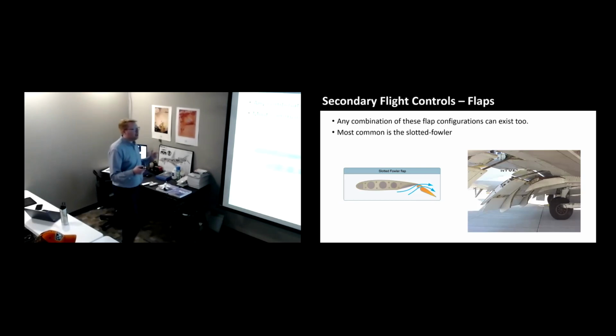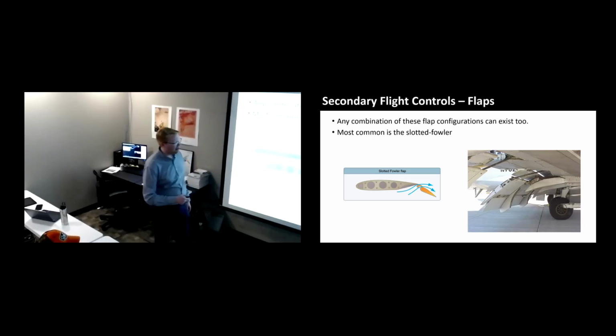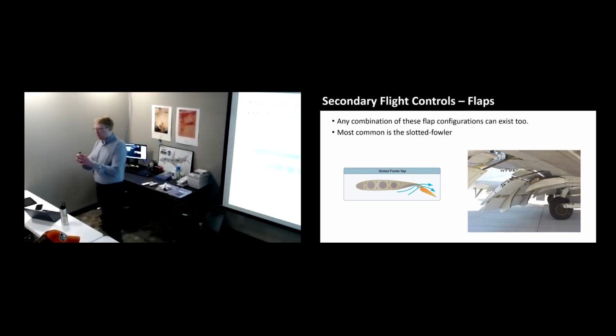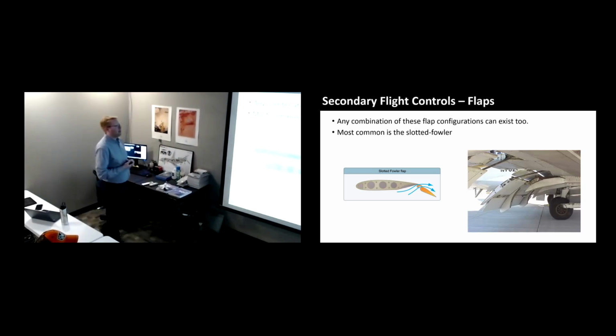If you take a combination of these two, I can't tell you exactly what airplane we're looking at here, but any airliner, name the one, will have a flap set up like this. Notice there are different sections of flaps, and they have little seals and gaps between some of them. This is a combo, slot and Fowler put together, a slotted Fowler flap. This is going to be your best design for your heaviest high-speed airplanes.